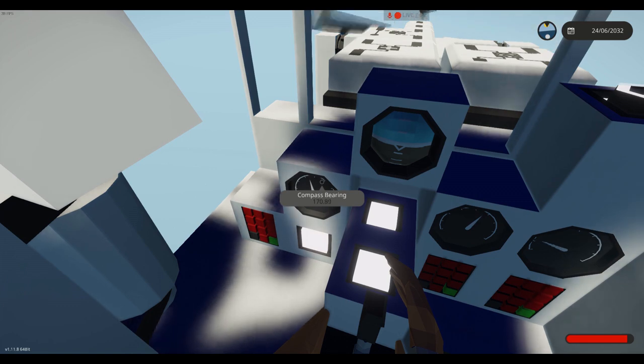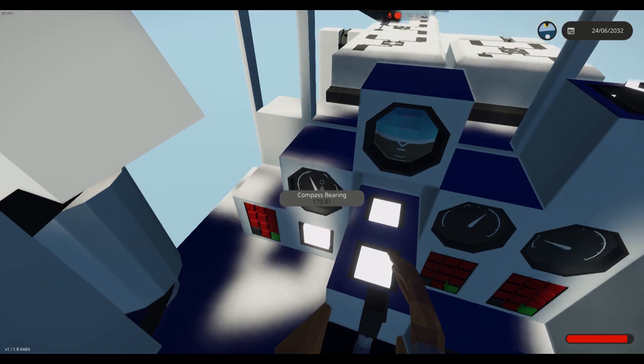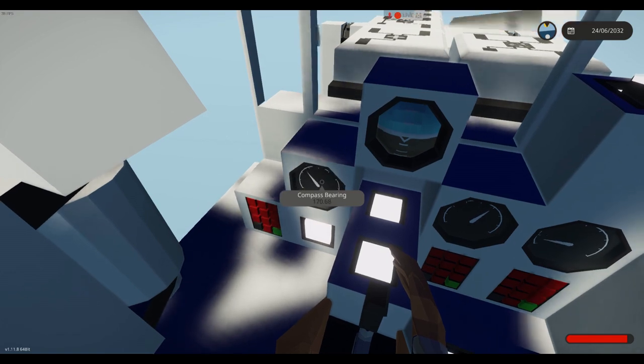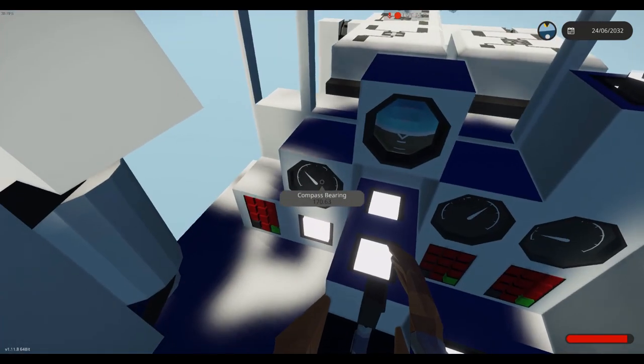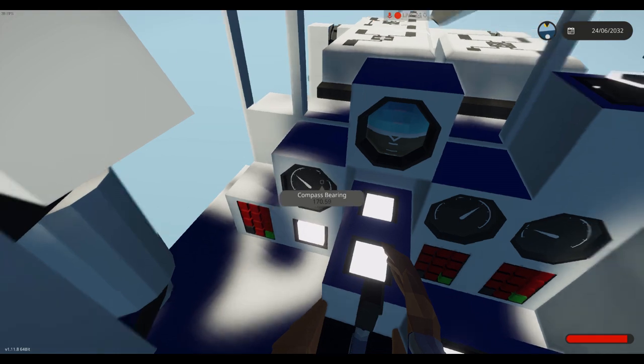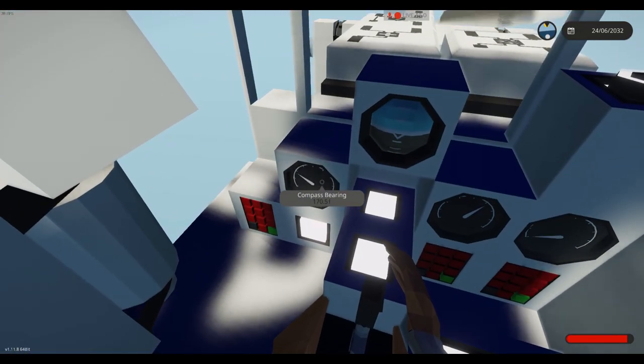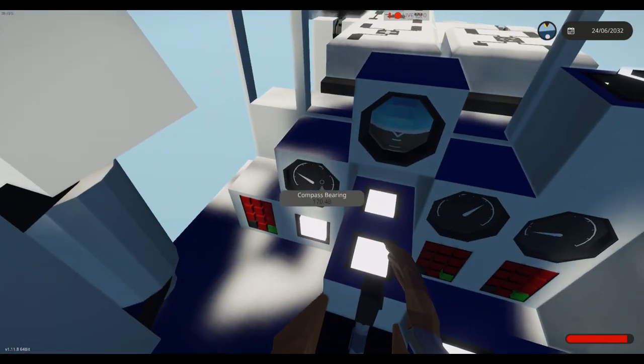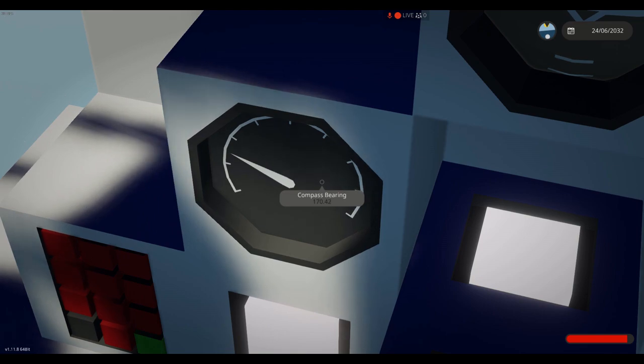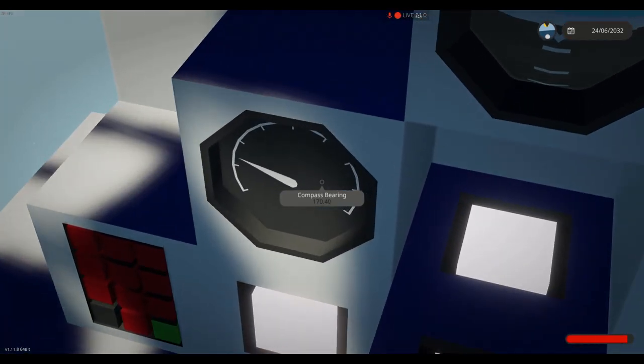For whatever reason, the engine throttle is kind of a very versatile thing. So your PID tuning for getting a speed hold system for the engine's throttle always seems to work pretty well. It does not require any fine-tune adjusting, really, hardly ever. However, the compass bearing hold system usually requires a lot of attention.